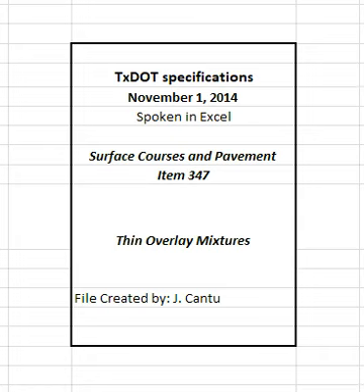Table 4. Test methods, test responsibility, and minimum certification levels. See table in specifications. 1. Level 1A, 1B, and 2 are certification levels provided by the Hot Mix Asphalt Center Certification Program. 2. Voids in mineral aggregates. 3. Refer to Section 347.4.9.2.3, Production Testing for Exceptions to Using an Ignition Oven. 4. Profiler and operator are required to be certified at the Texas A&M Transportation Institute facility when Surface Test Type B is specified.